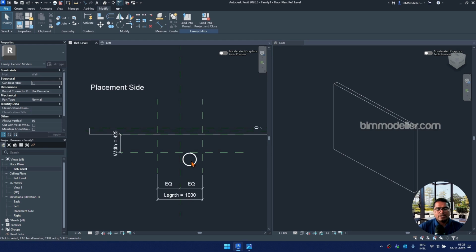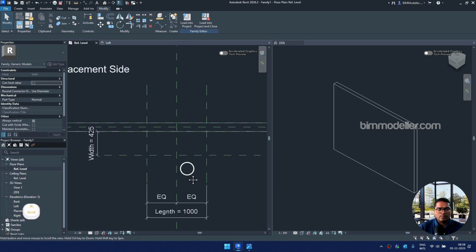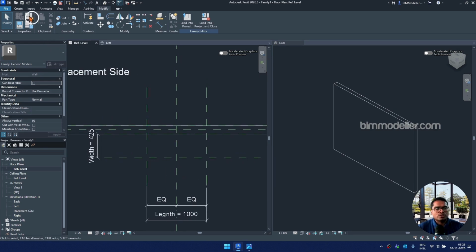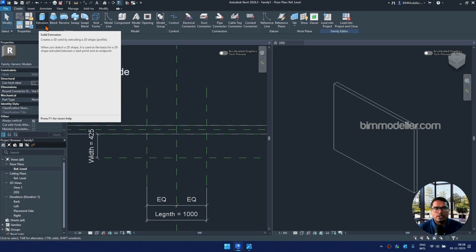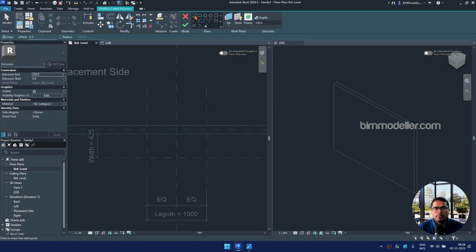So we have done the constraint and everything. So we have a proper setup here. You'll be able to start modeling it. So we have to plan it, as you know, if you're a fresher, we have to plan the constraint in the beginning. So we have planned our constraint and we are modeling the extrude object. So the beauty that we have here is that the dimensions are showing and the lock symbols are showing. We can lock them like these and finish it.